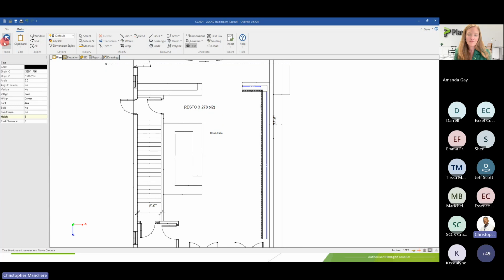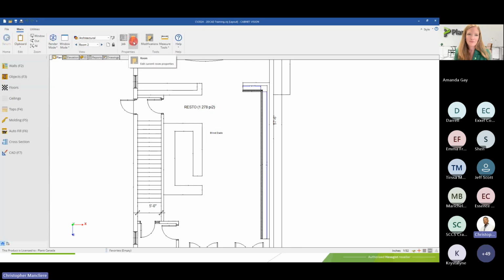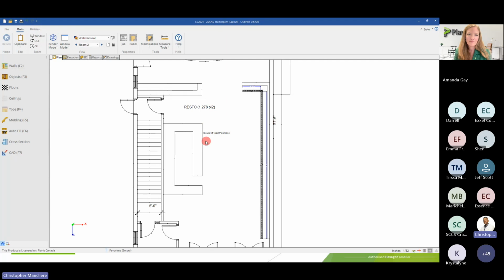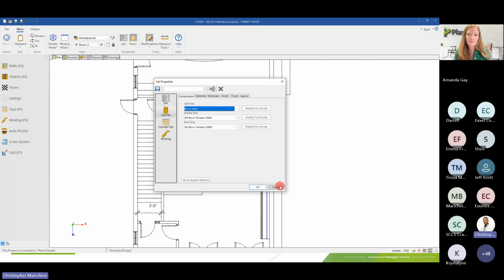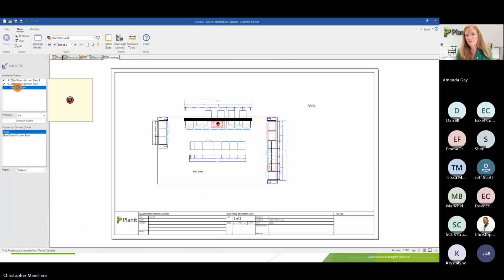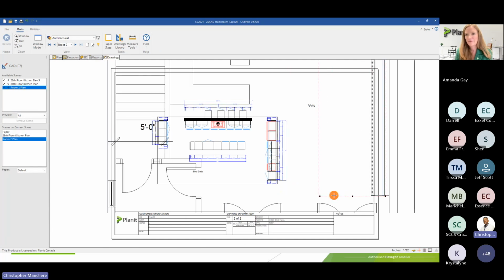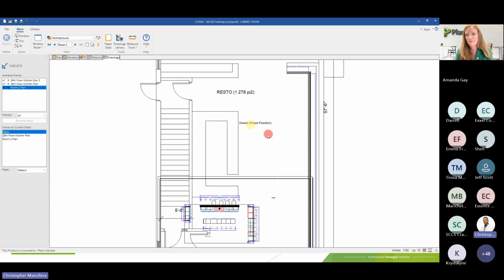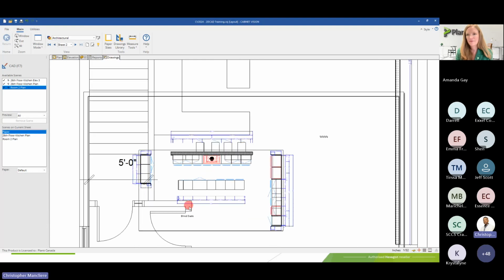Okay. And now this one, I will go at the room level, change, say this room will use dowel. Click OK. So because the code is tied to the room, even if my overall job is set to use blind dado, my room here is calling for dowel. So now this is going to reflect the properties of the room. And if I send this to a live drawing, I can put them side by side. And actually, it's so big, we won't see everything. But this is now dowel versus blind dado here.